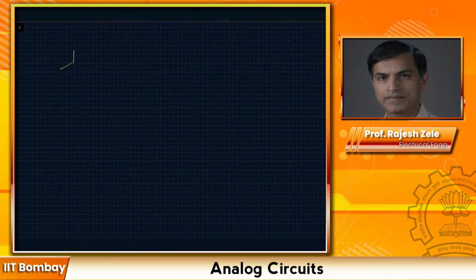If you just have a bipolar transistor and you do emitter degeneration, Re, what happened then? Our Rin was originally r pi plus beta times Re. So whatever is in the emitter gets multiplied by the beta of the transistor in the case of bipolar, when you are looking at the input resistance Rin. So by adding resistance Re at the emitter, we are able to increase the input resistance of the stage.